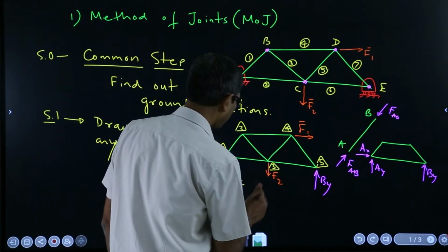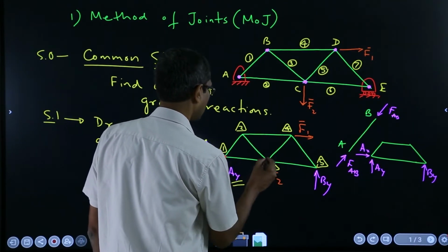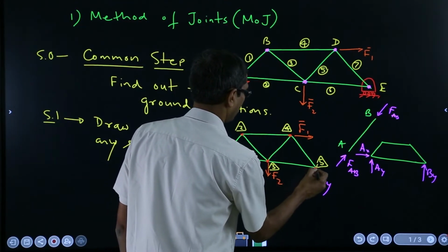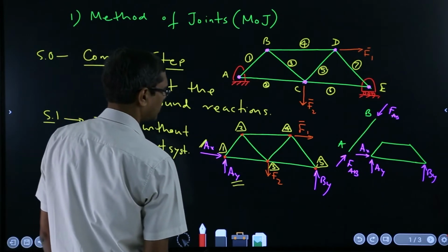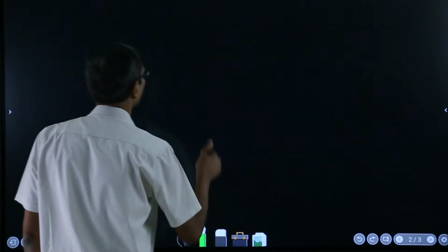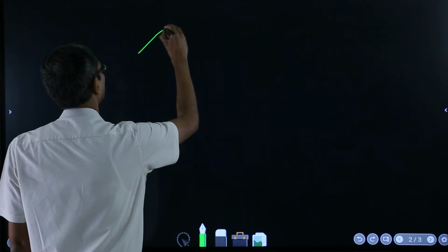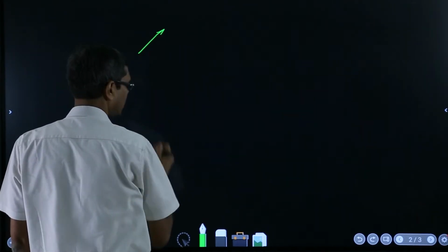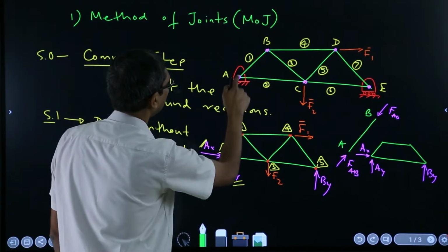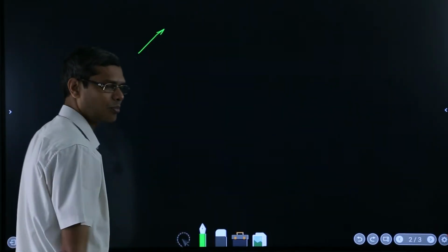Okay, but let me show even the joints here. Okay, so like that. So now if I consider, shall I go to the next page? Let me go. Okay, if I draw the point A, so there, one force is acting in the direction of, say, AB. I'll assume that it is a tensile force. You can assume anything you want, tensile or compressive, doesn't matter.